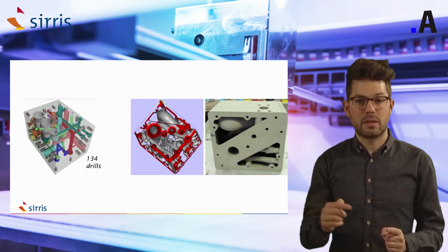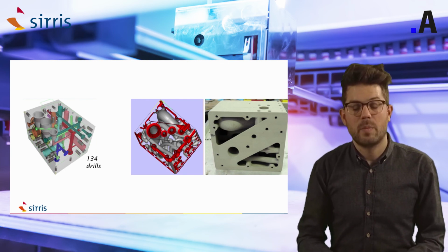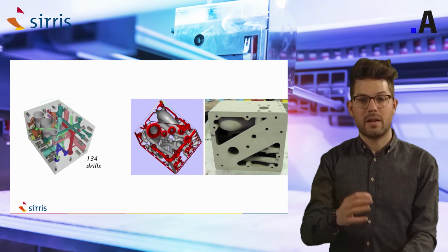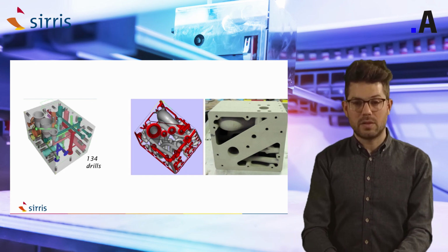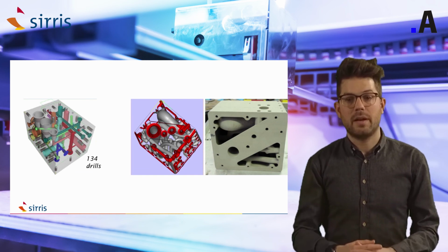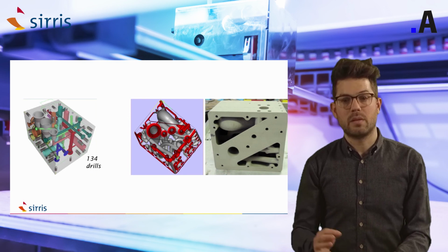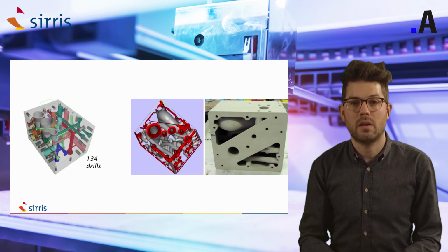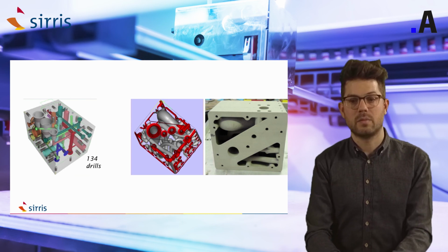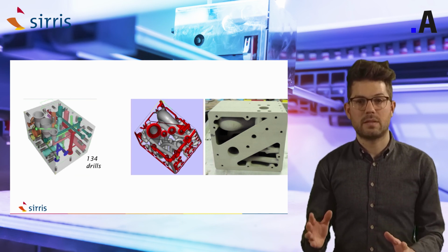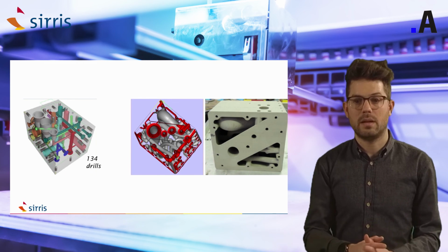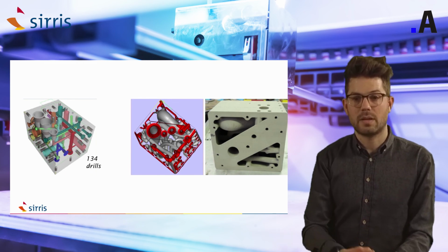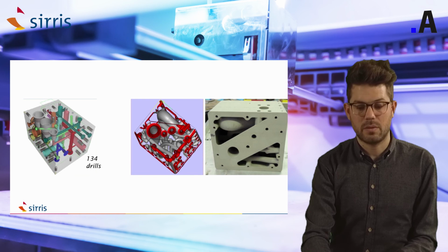and actually by using additive manufacturing, we don't risk having defects during the drilling operations, because we can just design the channels along each other, and then we only print the functional material, which is a certain thickness around the channel, and some material to fix the complete part within the assembly. And you can see a picture of the part on the right.